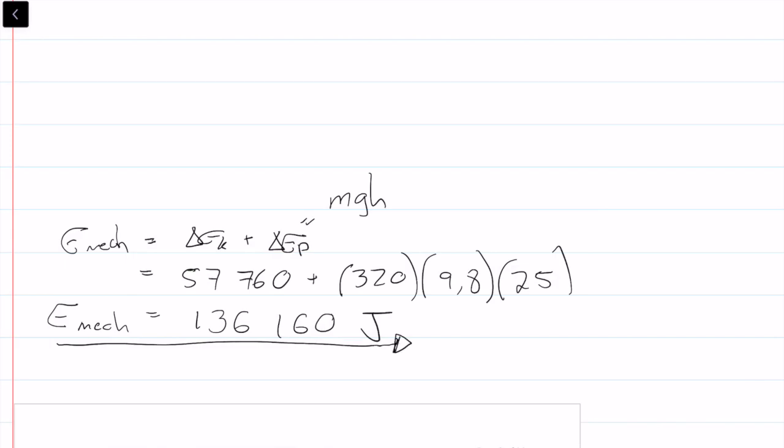So basically the increase takes into account the kinetic energy and the potential energy, and the reason why we're saying it's an increase is because we worked with velocity final minus velocity initial, and this we could even say is height final minus height initial, and the initial height is being used as the datum of 0.